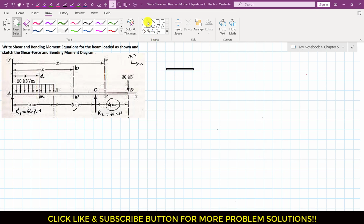Here we will have that R1 is 63 kilonewton, and from this point to this point we have that distributed load, right, and this is 20 kilonewton per meter, and the length of this section of that beam is x, right? And at the right side of this cutting section we will have the internal bending moment, like this. So let's say that this is that bending moment, and here we have that shear force. Let's say that shear force is represented by V, right?